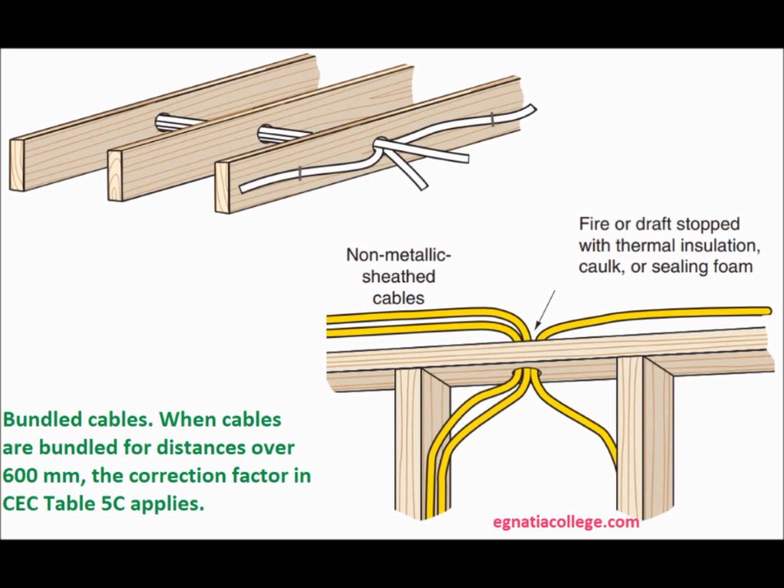The spacing requirements are 25 mm to heating ducts, 50 mm to masonry chimneys, 150 mm to chimney and flue cleanouts. The spacing may be reduced if an approved thermal barrier is placed between the conductor and the heat source that will maintain an ambient conductor temperature of 30 degrees Celsius.